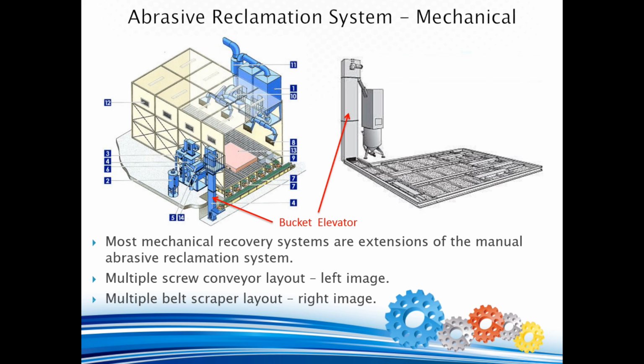Besides the civil works construction costs and pit drainage considerations, another key consideration for mechanical media recovery systems is wear and tear during use. Because of the abrasive nature of spent media being recovered, both screw conveyor and scraper systems are under heavy abrading action during use, so the use of wear-resistant materials in the construction of such systems is absolutely critical to keep equipment downtime to a minimum.